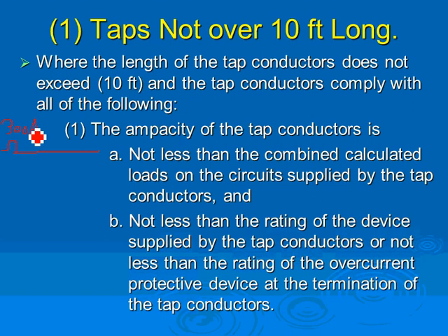310. But so for 300 amp, 280, yep, I can go to 300 kcmil because for 280, the next standard is 300. Taking into consideration that one is 285 amps, the next standard is 300, so I can go for 300. So the conductor size here is 300 kcmil. Cool. And then I bring that baby in a gutter and I tap it.